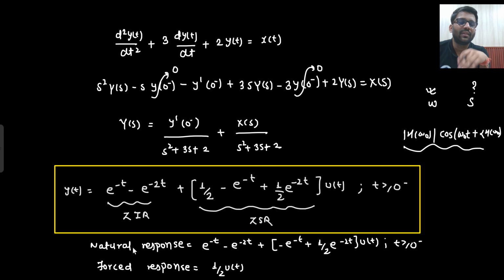But in S domain, if I talk about poles, here the poles are there, and here this is the ROC. So you will be able to tell whether it is causal, stable, and all these kinds of things. So to comment on the nature of h(t), S domain is used. Because from omega domain, you can only comment what kind of filter it is. And if it is defined in omega domain, that means it has to be stable, then only it will be defined.